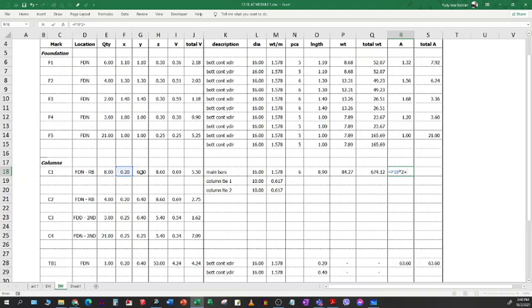And the second phase is 0.4, then we multiply it by 2. And then all of those things we multiply by the total height, which is 8.6. 10.32 all in all. And then multiply that by the total number of columns, 8 times 10.32. You will have 82.56 square meters for the entire C1. Now let's go to the column ties.